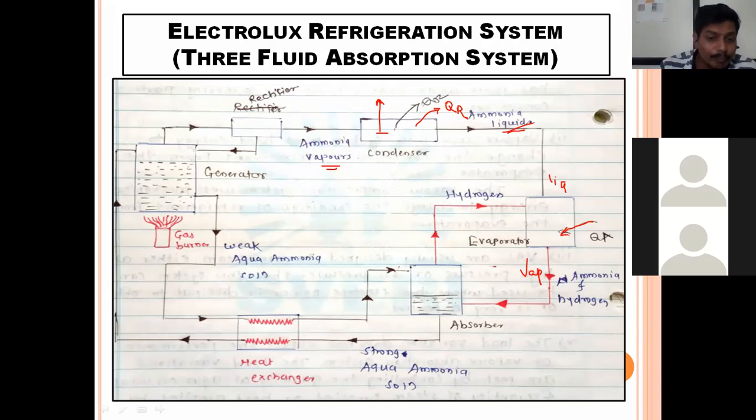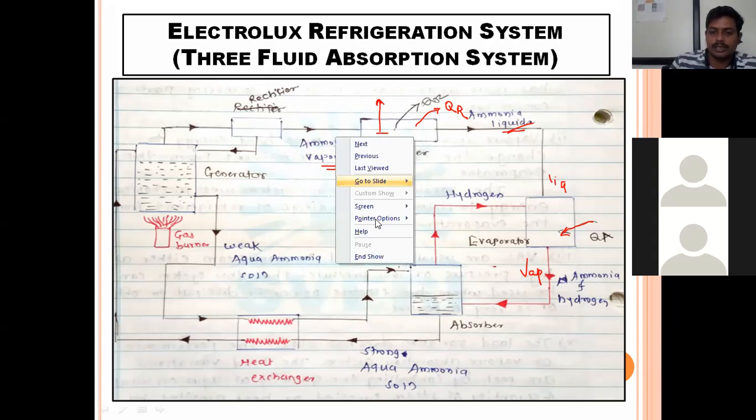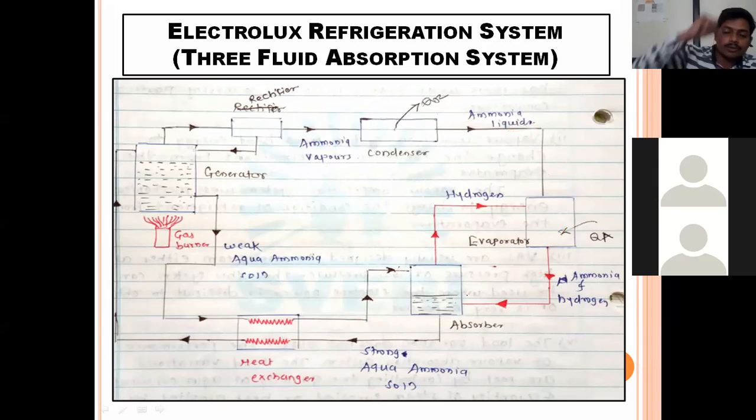But here, in case of the three fluid refrigeration system, or in case of the Electrolux refrigeration system, as we are not using a pump, hence the pressure throughout the system will be the same. Pressure throughout the system will be the same.